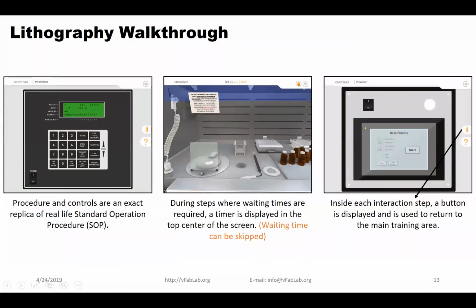During steps, you can press these buttons to have the process recipe loaded. It does not mean that if in a real-life environment I set 30 seconds with 2000 RPM, it's going to be exactly similar, but it will give you a feeling of what you can expect if you're running it in that kind of environment.